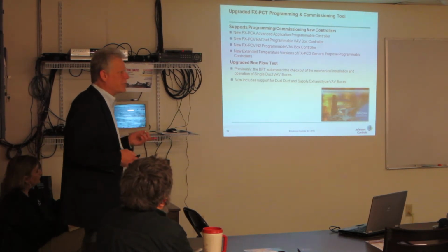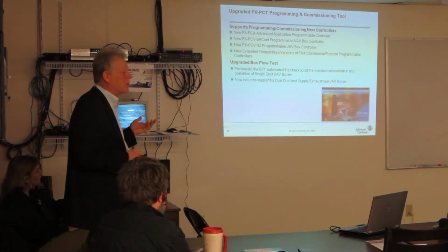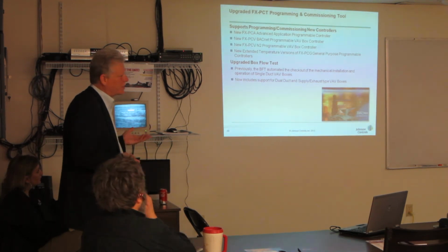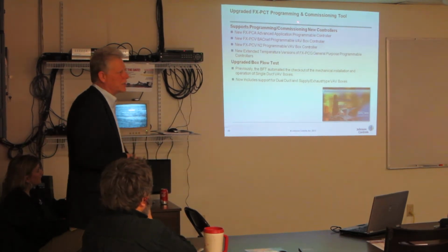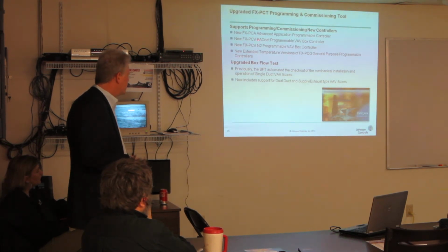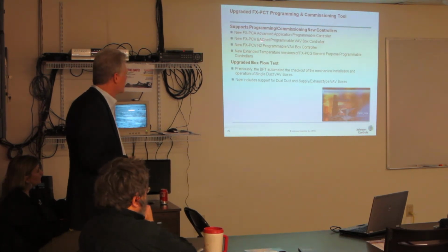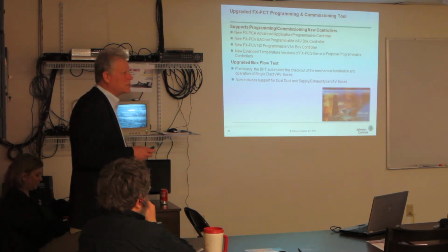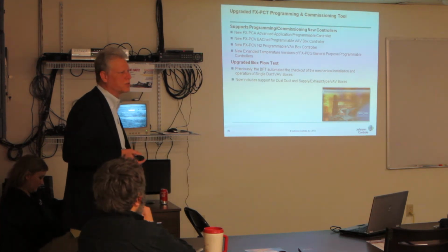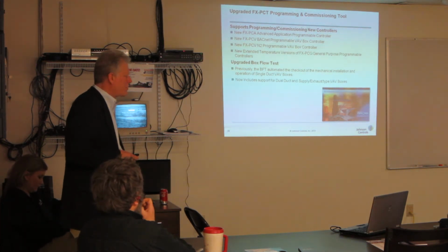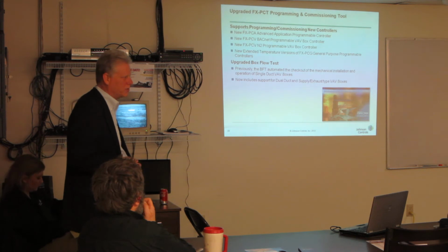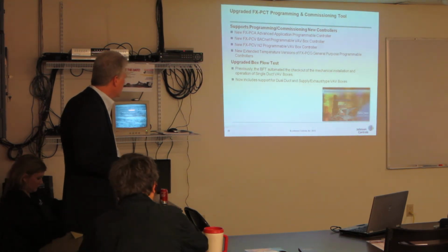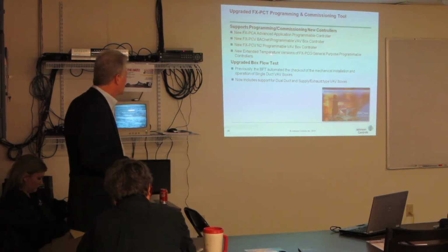But what's going to be released in that, also in 6.0, is because you'll have to get that because the new controllers will be listed in there now. So the PCAs, the PCB BACnet, which is the VAV controller, BACnet controller, will be in there now, and also the N2. Again, you use that same PCT software to configure the new N2 controllers also. You won't use HVAC Pro anymore. And then also the extended temperature.